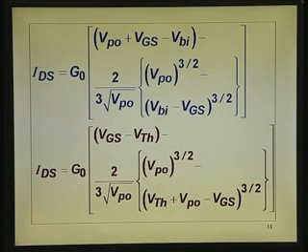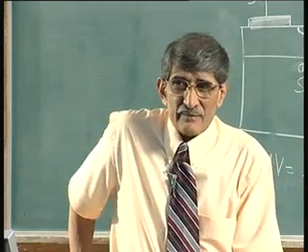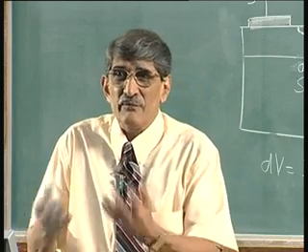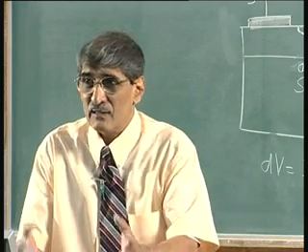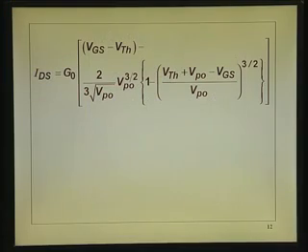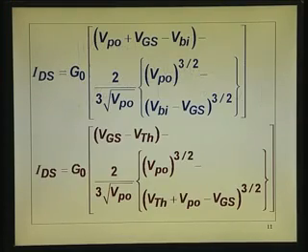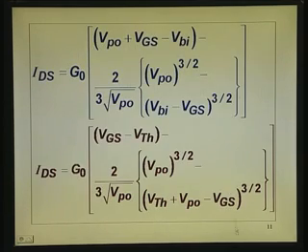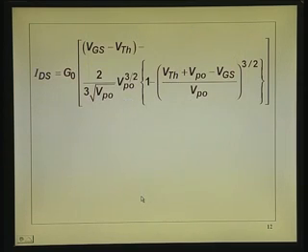There is no more concept involved, all the concepts have been crystallized. All that we are doing is just manipulation of this equation to bring it into the form that we usually see in the case of MOSFET. So, rewriting this, again substituting for Vp0, we get Vgs minus V threshold as the first term, and the second term is retaining the same thing.